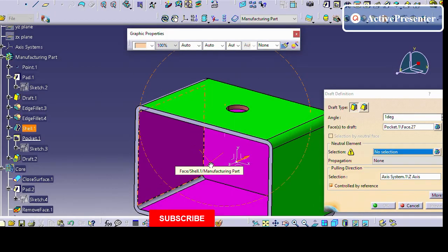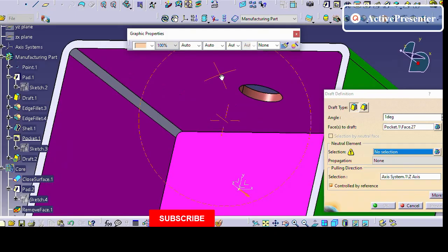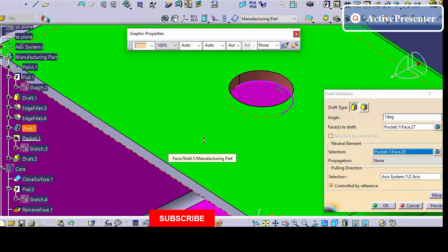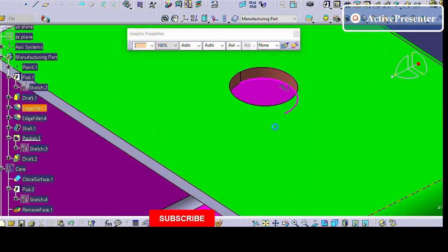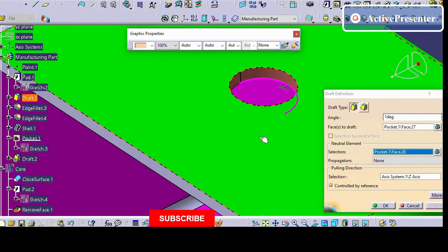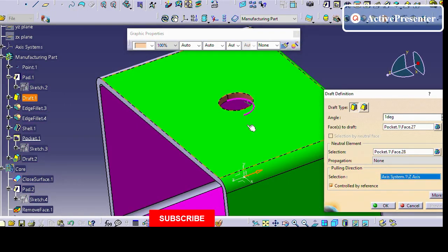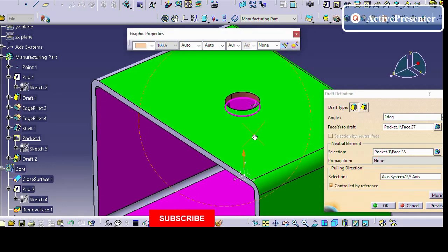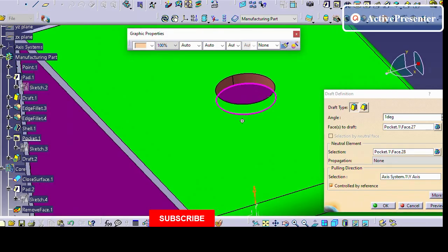Neutral surface. The reason I am going to move my slider in upward direction. So it will be at the bottom. Correct. So that once I selected the bottom, this is my tooling direction, like this slider direction. I will tell you how to create the slider direction separately. We need to create a slider direction and tooling direction, main tooling direction. Okay.